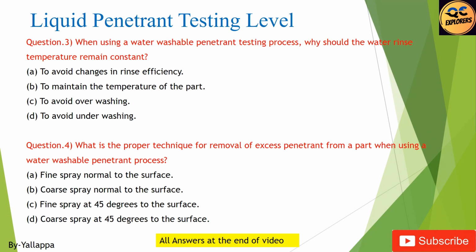Question point 3. When using a water-washable penetrant testing process, why should the water rinse temperature remain constant? To avoid changes in rinse efficiency. To maintain the temperature of the part. To avoid overwashing. To avoid underwashing.